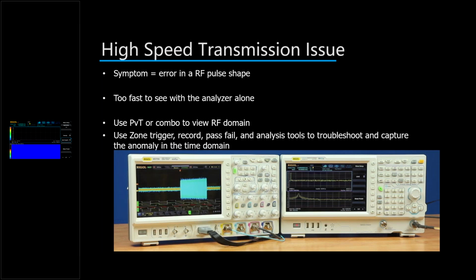One thing we can do is go into our density spectrogram, and here we can clearly see the duration of these pulses as the waterfall chart shows how it's moving through. We can also switch over to our power trigger, so now we're capturing just the pulses, not the blank time in between. Now we're able to adjust that power level and capture those pulses, and we're triggering out to the oscilloscope and capturing some pulses there also.